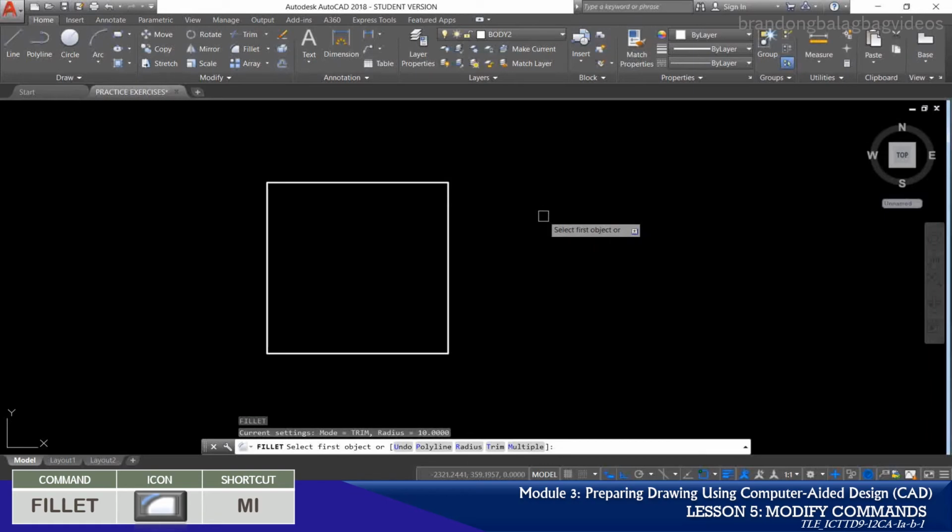When AutoCAD asks you to select the first object, there are also other options available. It's either undo, polyline, radius, trim, multiple. Usually, a fillet is made by using a radius. So let's type in R to represent the radius, and then AutoCAD will prompt you to specify the fillet radius. In this case, let's make use of 5 as our fillet radius. After typing in the given radius, just press enter.